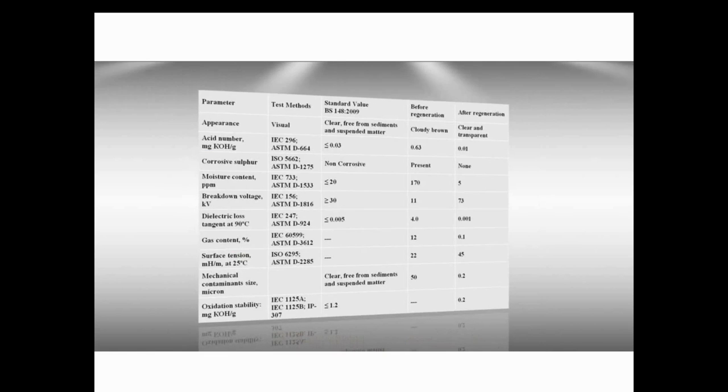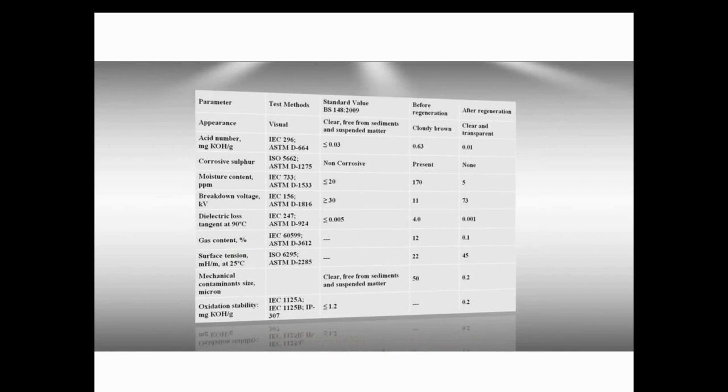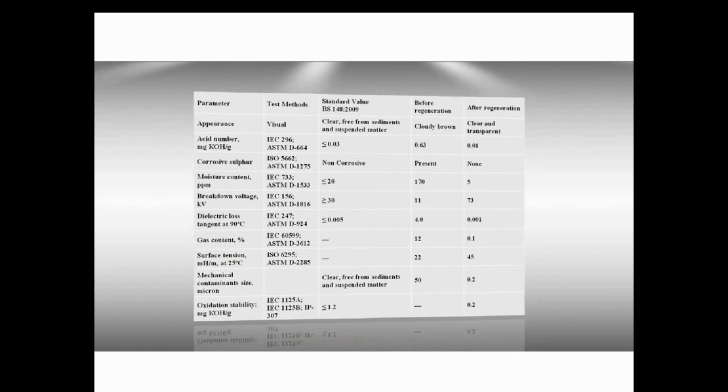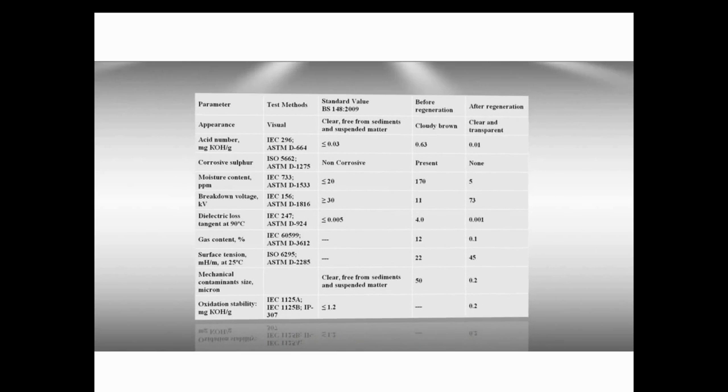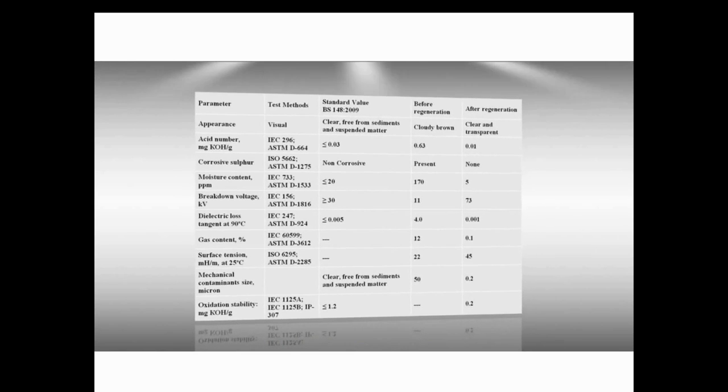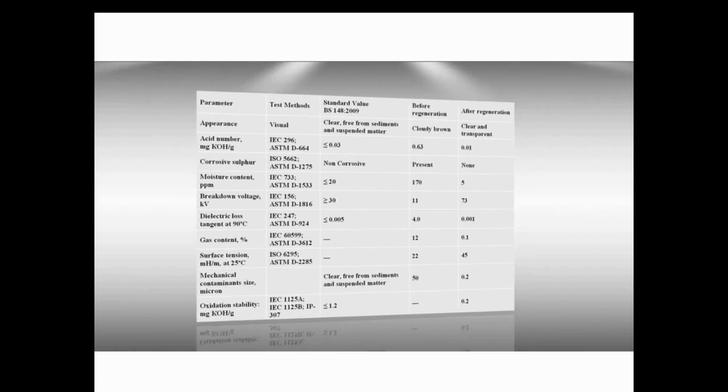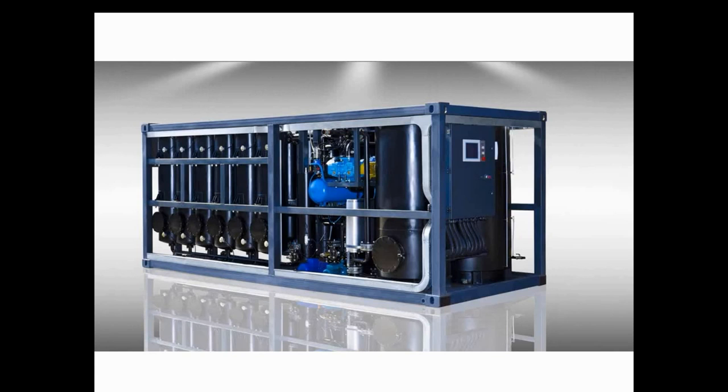Here you can see some results of oil tests carried out 2 years after regeneration. Especial attention we should give to acidity, breakdown voltage, resistivity, dissipation factor, oxidation stability, and interfacial tension.